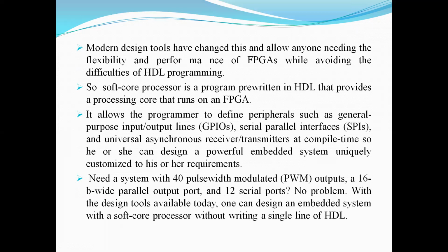So, a soft core processor is a program pre-written in HDL that provides a processor core that runs on an FPGA. It allows the programmer to define general purpose input-output lines, that is GPIOs, serial peripheral interfaces, that is SPIs, and universal asynchronous receiver transmitters at compile time, so he or she can design a powerful embedded system uniquely customized to his or her requirements.